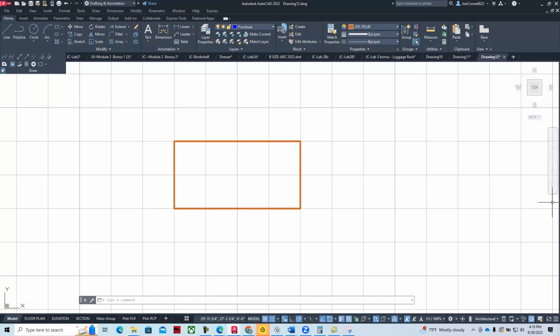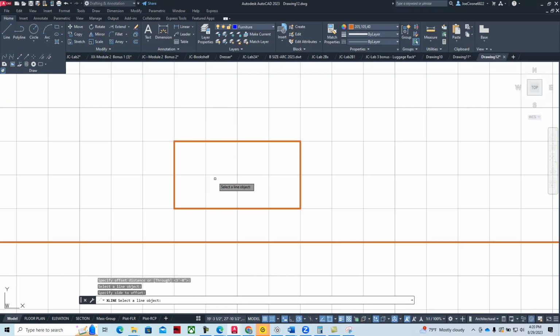I think maybe they exploded it and then they offset it to get that at the right angle, because mine is completing the whole thing. So if we explode it, now these are individual lines, and then we use offset. It's a lot more than it's showing in the textbook, and it's going 3 feet, so I'll draw an infinite line here, turn off my O-snap.